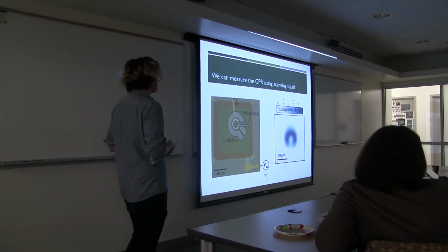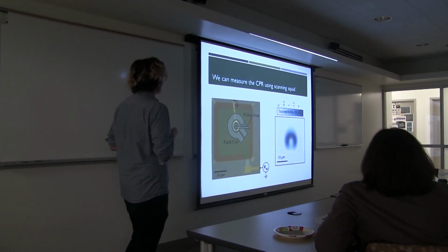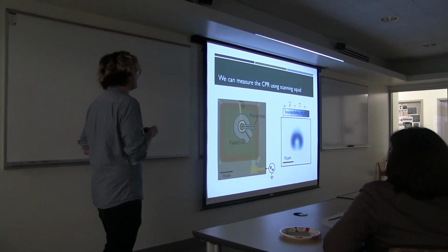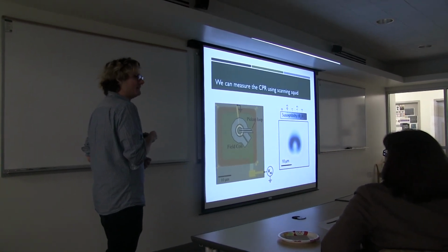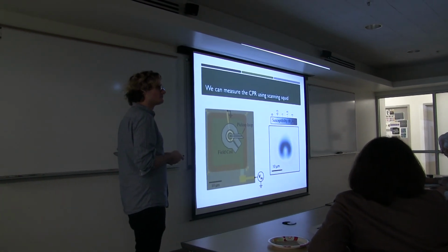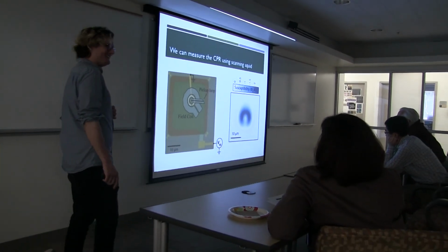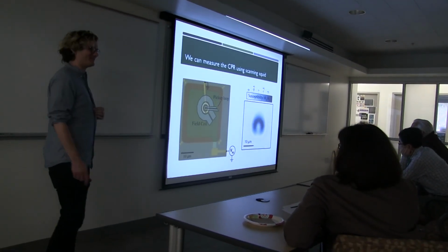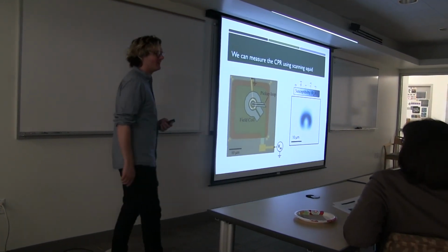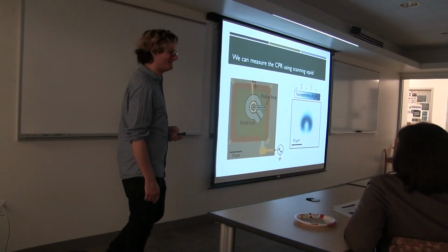And that arm going away from that is aluminum? This is gold. So there's a little tab here. And actually, if you go close to TC, you can see that the inverse proximity effect from the gold kills superconductivity here, like 10 millikelvin before superconductivity everywhere else does. So that tab doesn't keep your electron temperature lower? It's not an isolated ring, yeah, but the filtering in the fridge has gotten... I need to double check whether this line is filtered or not. But our fridge no longer has a radiation shield, and so that might have something to do with it.